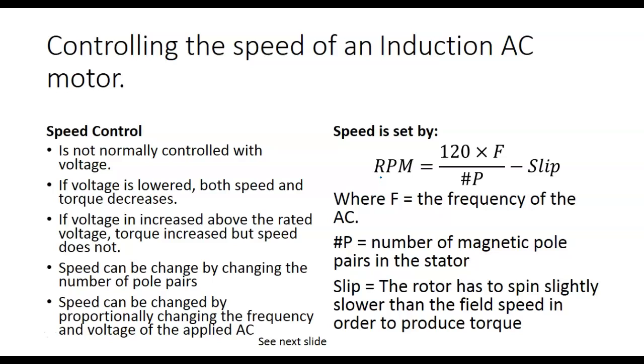If I just change the frequency, we'd burn that motor up. The problem we have is that the motor is an inductor. If you have AC, the opposition that motor has is 2 pi F L. So that's frequency. If I raise the frequency up, the opposition goes up, so the motor would stall. If I lower the frequency, then the motor would burn up.